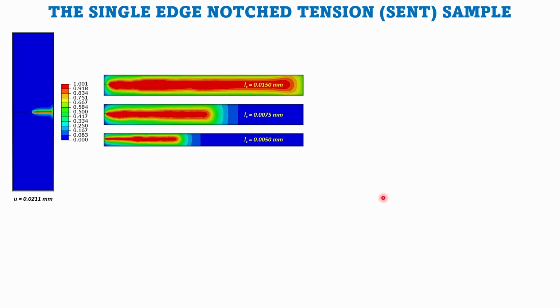now this picture I showed, I think, in my first video when I was showing a representative phase field simulation. I'm showing it here again. This is what the typical crack pattern of a phase field simulation looks like. You have a band. You see, you don't have a sharp crack. You have a contour, or you have a band.